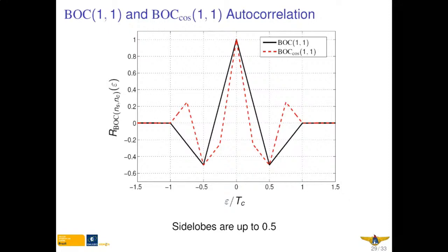synchronization process, because as you have seen earlier, the receiver tries iteratively to track. It is initialized somewhere here in this area of this autocorrelation function, and then tries to find the peak and tries to track the peak. However, if we initialize farther out here, or if there's a lot of noise, the delay lock loop can slip out here, and we can maybe even get stuck in a side peak. And this is what I mentioned earlier with synchronization robustness.